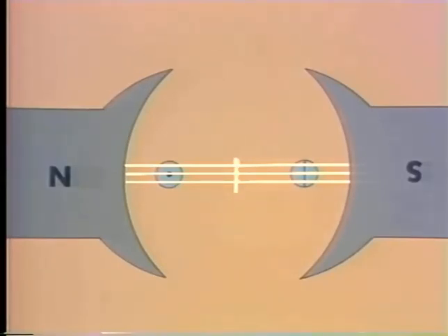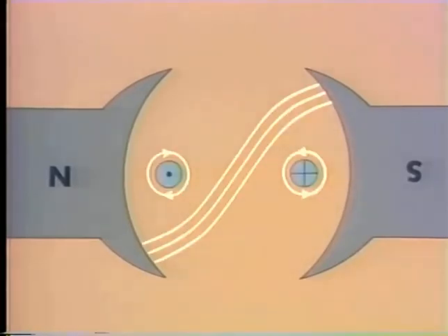Now, when voltage is applied to the conductor, the magnetic field shifts, so the position of the neutral plane is now here. So it's the place at which the brushes in the motor can short the conductor without doing any damage. Shorting the conductor when it has current flowing through it will cause sparking. The heat from the sparks could damage the commutator segments. To prevent this from happening, you must compensate for shift in the neutral plane.